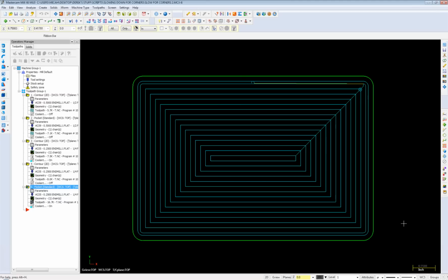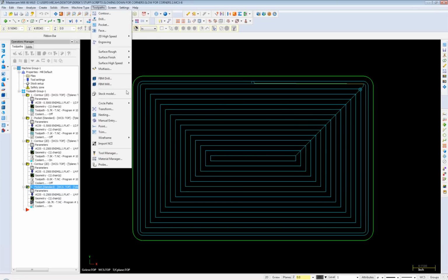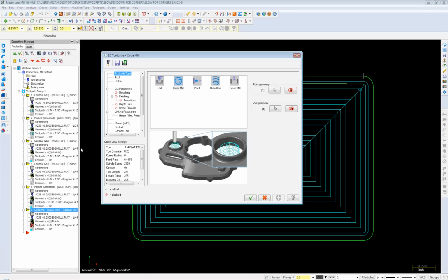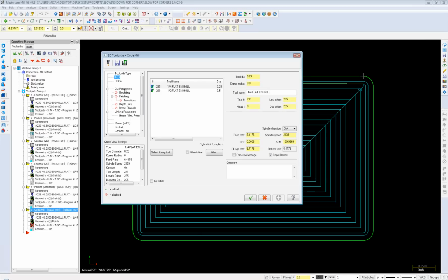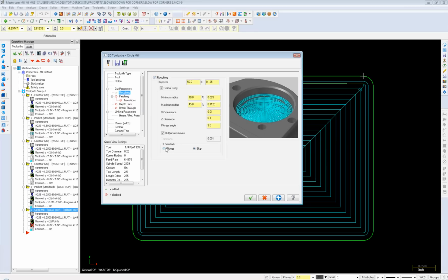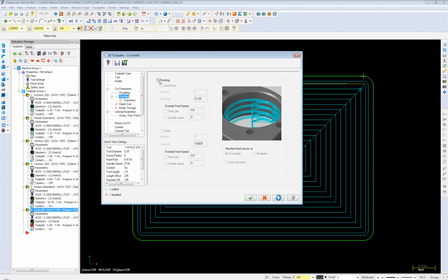John is responding there with a follow-up. So it seems like you set it to start at center and move out, and it looks like he's getting a feed rate that's too fast on that initial move. So I don't think that's a high feed function. I'm not sure. John, if you want to output a G code, do a test file, just do a circle mill in a Mastercam file and also output the G code so we can take a look at it. If you send us that file, we'll see if we can help you a little bit more. Send that in to either Jay or Mike or Derek or Micah at eapprentice.net.